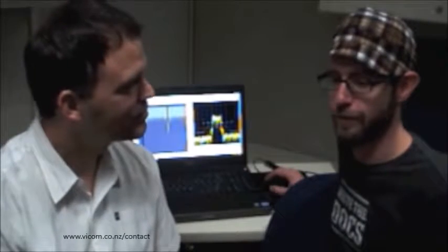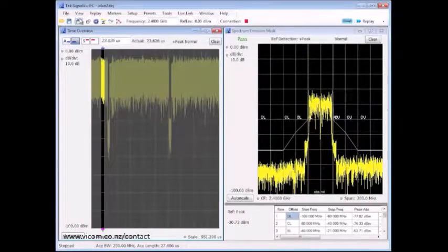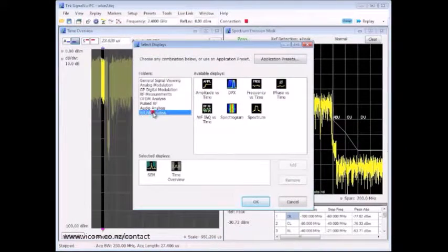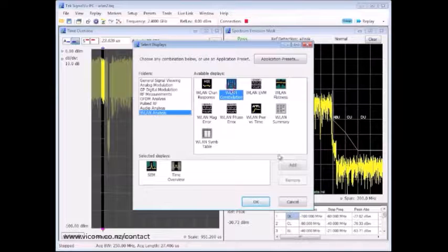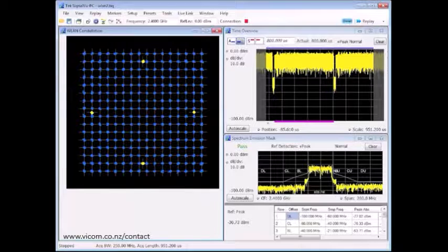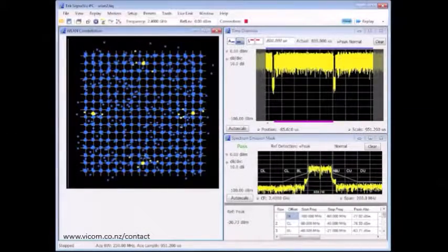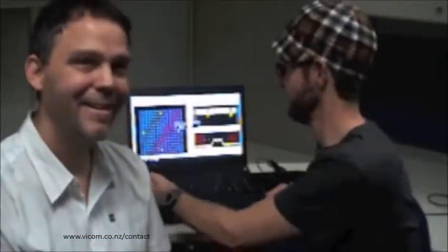Yep, the constellation diagram. So this gives us a clearer picture of, are we actually transmitting a clean signal? This has always been an interesting one to me. It's a clear indication. I love this. You can see right away, is my signal hopping around in the phase space the way it's supposed to? This one here is perfect, right? I mean, it's pretty good. Now, as our signal gets dirtier, our stars in our constellation start to look a little more like nebulae. We get something like this. Oh, we don't want that.